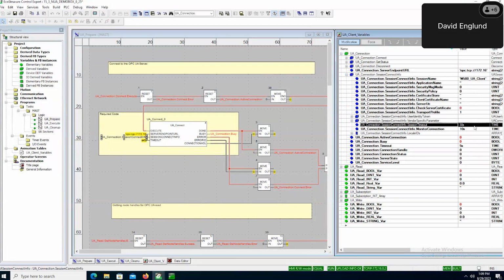This is just telling the server and the client, hey, if we lose connection for more than 30 seconds, clean this session out of your memory. And then we also have a monitor connection here. The PLC will basically just do a keep alive every 10 seconds in case you're not actually doing anything, like you're not really reading or writing data or subscribing to anything. You'll notice a lot more variables we could put in here as part of the data structure, but these will come in later releases to be used with security.